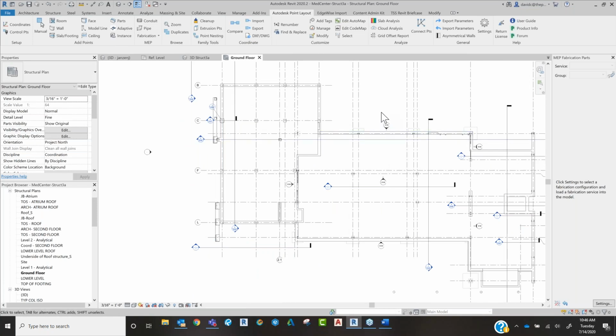Now, typically you can do that, or what I like to do is actually use some detail lines, and maybe I'll go out from a column about 20 feet and maybe take the next column down 20 feet, meet somewhere right along the grid lines, and I'll place my control points there. Just because when we get into an actual building, we're not going to be able to calibrate based off the inner portion of that column. So I'll give us some offset from that to help us calibrate it.